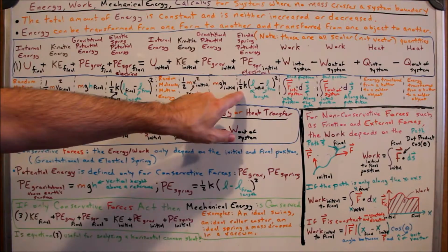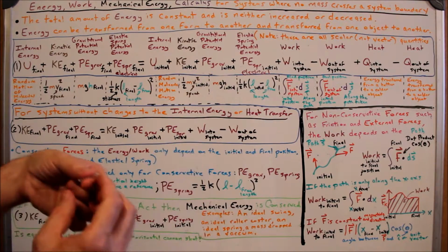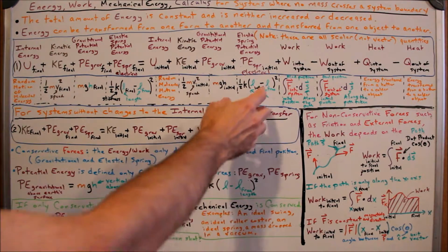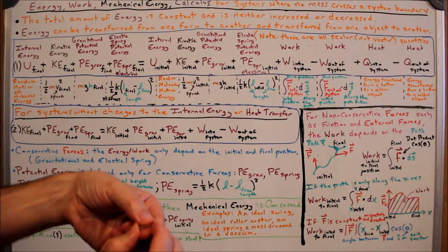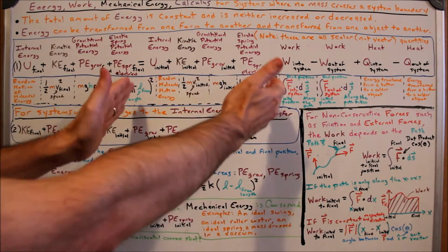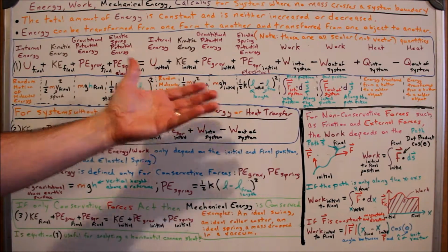And then the potential energy stored in it is 1/2 the spring stiffness times the square of the difference between the length of the spring at this initial time minus the free length. So that's kind of my initial energy term summation of my system.